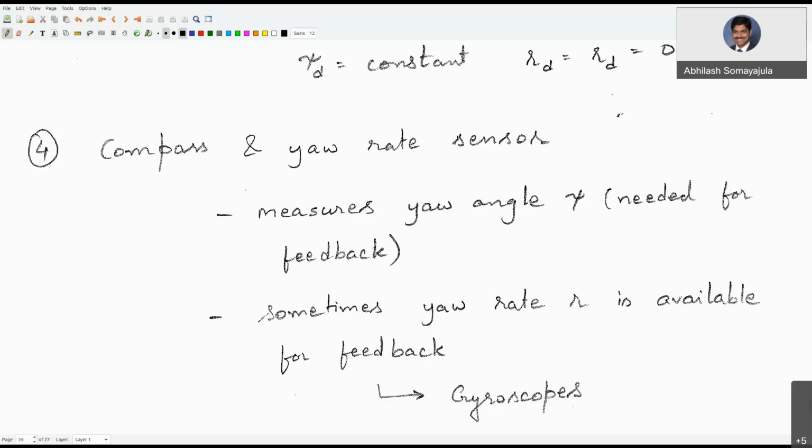And many times we are looking at a fusion between the IMU, where it is looking at the accelerations and the angular velocities being fused together in order to obtain an orientation vector or the quaternion vector. Again, that is not valid when you are discussing aircraft. That is where it will fail, because all of this is assuming that the gravity vector is always pointing straight down. But if my craft is maneuvering at 4G or 5G, then the accelerations themselves are more than the acceleration due to gravity. So in that case, the orientation vector cannot be obtained using the methods which are used.